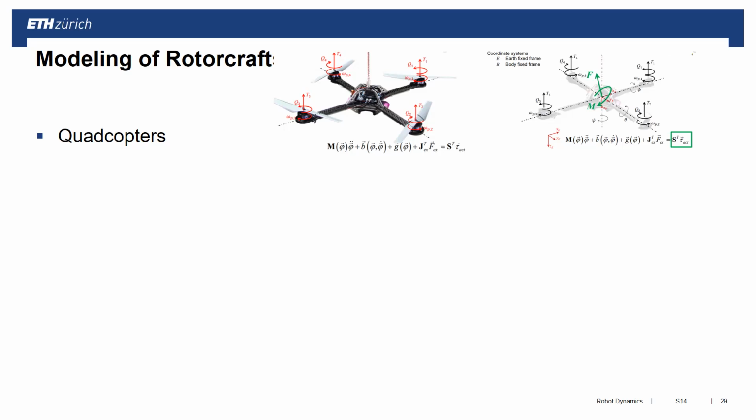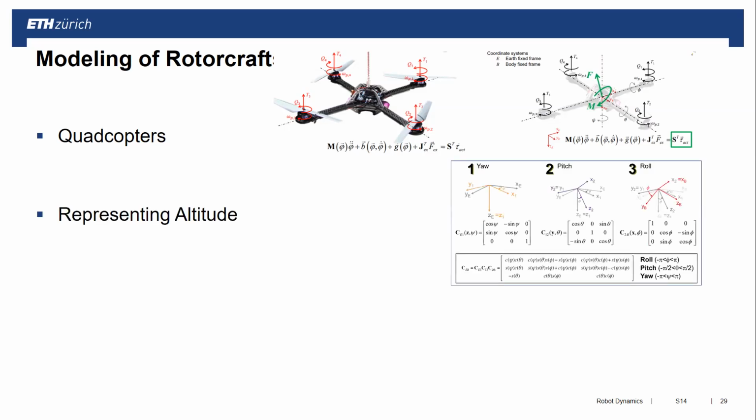And again, this brings us back to these forces and torques applying in our system. Instead of coming from external forces through constraints, here these forces are coming through thrust and drag at these individual props. We looked at representing the whole attitude, most often here with Tait-Bryan angles, so roll, pitch, yaw.